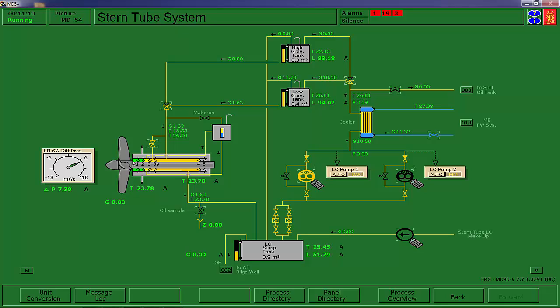On the other hand, if the sea pressure outside the propeller gets too high, then the water can push through these lip seals and get into the bearing. That's a very serious thing to happen, because the oil and water will not lubricate properly, and you'll get excessive wear and corrosion of the stern tube bearing. And stern tube bearings, that is not a cheap item to replace. Think about how much time and money has to go into removal of the propeller, removal of the main shaft, and then pressing this huge bushing out of the hull.